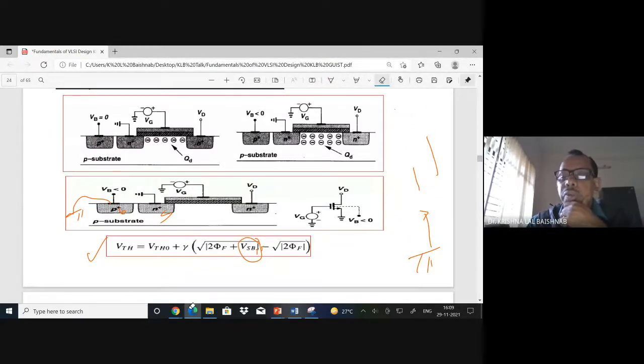I'm just showing you one amplifier design, a simple amplifier design. I'll take the driver as an NMOS, the driver transistor, and put it in the ground. And this is my output, and here I make my PMOS circuit.